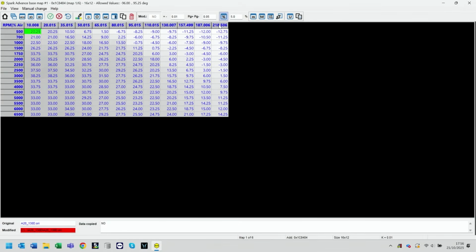Now we've changed the logic in the ECU, the strategy of the ECU, but this has a knock-on impact because not all of the tables have now been scaled to the same point. And this is the difference when you start getting into quite heavily modified vehicles, really pushing the maximum of the standard components. It can be done without making changes to the axes, but it does require data logging and validation of the changes to ensure that the car is running safely under those conditions.